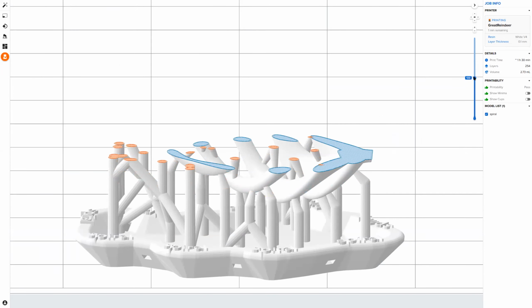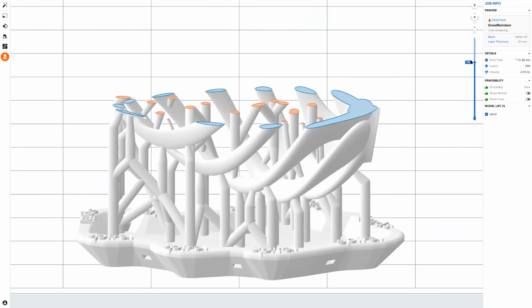Sure. If we assure that the resin can pour out, can we use infills? For example, by building chambers and keeping a hole so we can drain the part after the process is over? Yes, you can do that, but you need to be careful. The software is not actually allowing you to do that, but if you are printing or designing a custom machine, you can do that. Another issue is that you should be washing it properly. You shouldn't have any uncured resin inside.